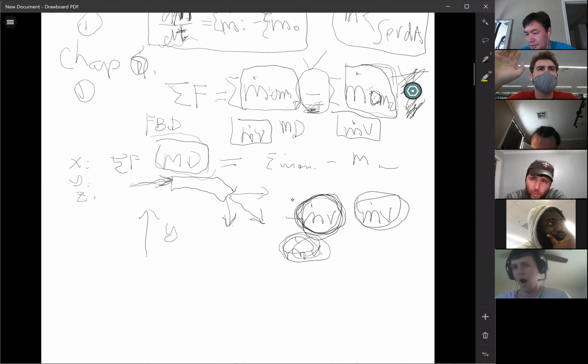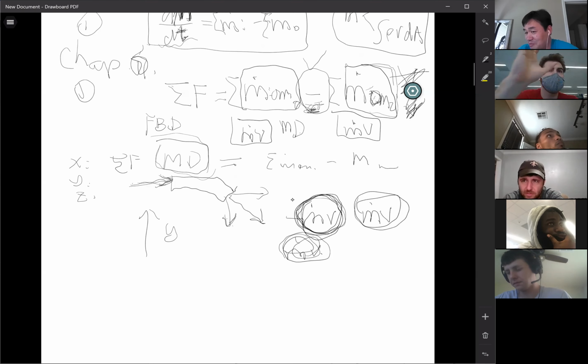We had a Z, but it didn't change in the Z direction. If there's no momentum in the Z direction, it's just the force balance, the hydrostatic, in the Z direction, because there's no flow, no momentum along the Z direction. The fluid is not moving along the Z direction, so you don't have a momentum. Okay, so momentum equals 0.